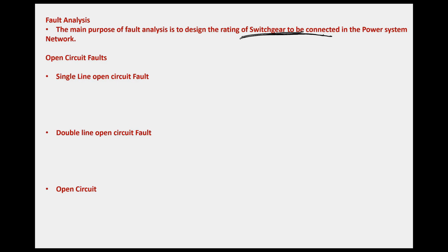Okay. Suppose in your house you are using a 4-ton AC, and for that 4-ton AC, you are using a 10 ampere or say 20 ampere MCB for protection. If a dead short circuit happens inside that AC, let us assume the highest fault current that can flow through that AC momentarily is 10,000 amperes. If there is a short circuit in the AC, it can carry a fault current of 10,000 amperes.